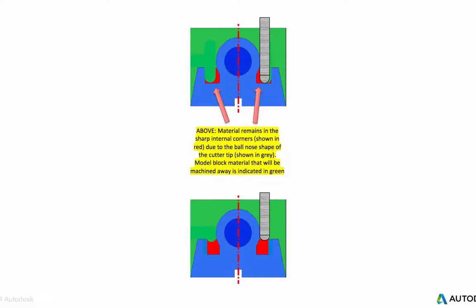This example is a similar body profile to the previous. However, here the slot down next to the left and right sides of the CO2 canister housing is not as wide. The slot is narrower than 1/4 inch, and therefore the cutter cannot access and remove the material in red. Any slot or groove feature like this that is narrower than the diameter of the cutter cannot be machined.